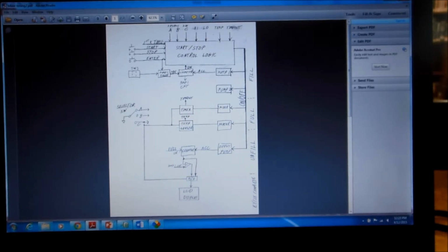And here it's different from when I was doing this after post-production, when we did the actual program. I was saying, well, we should put that in the preset value. The actual implementation is a little bit different. I put in a register, and then I have that register compare with the accumulator, and when the comparison is equal, then I stop the pump. And this is probably the better way to do it, is put it in preset.